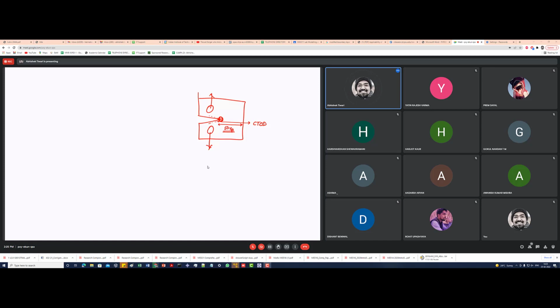For that small area, if you want to find out the stress and strain, you will have to have a very fine mesh there, with very small element size. If your plastic zone is, let us say, 1 micrometer, you cannot just have one element there. You have to have at least 100 elements there, right? So that small amount of meshing becomes very complicated. You will have a very huge number of elements in your calculation, and this will be a burden on your computation.